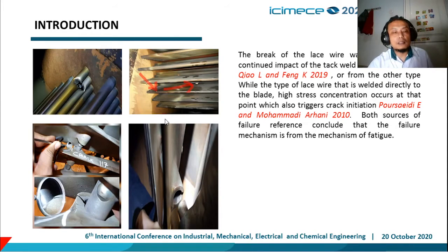The break of the lashing wire was driven by continued impact of the shroud, lashing wire and stub, according to Xiao and Frankie in 2019. Or, for the type of lashing wire that is welded directly to the blade, high stress concentration occurs at the point, which also triggers crack initiation.